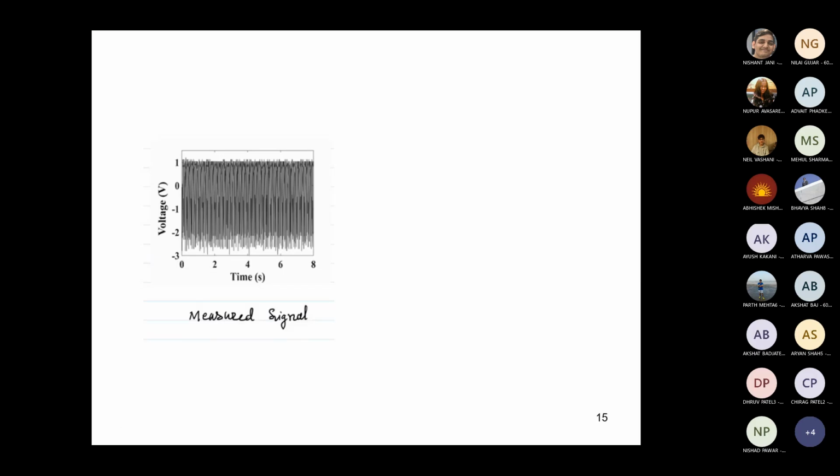You attach a vibration measuring device to that shaper machine, take the readings, read them out on the computer, and then feed them to the FFT analyzer, or to MATLAB, and do the fast Fourier transformation on this. So what will I get?